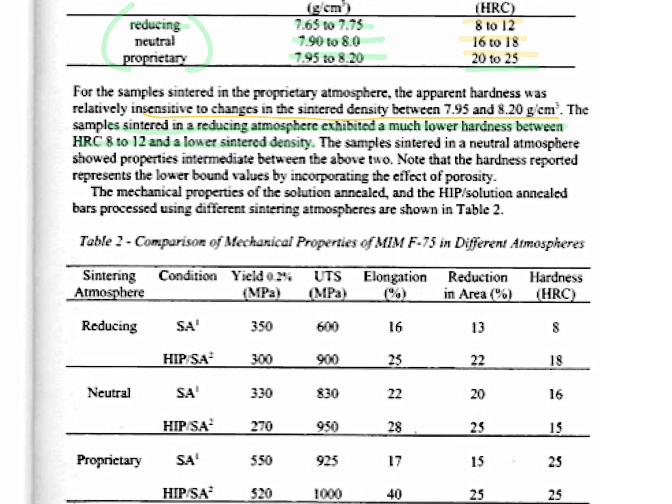The second one, carbon. All right, you already got the oxygen out earlier. Now you're pulling out the carbon. So he's saying that you don't want to do too much of this reduction. You do want to remove the oxides, but you don't want to take the carbon out. At least you don't want to take too much of the carbon out.